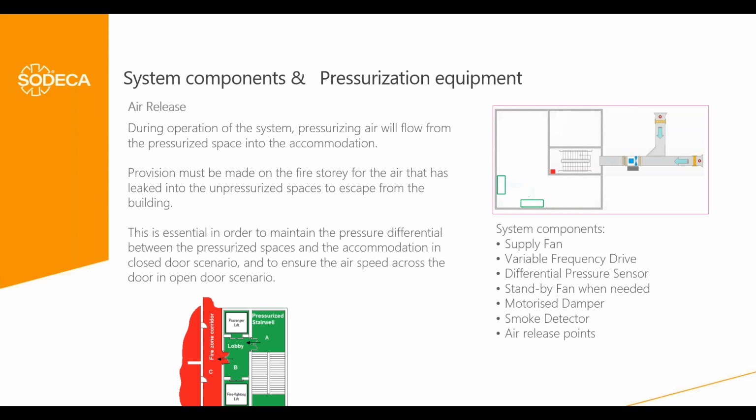The same applies in the door open condition. If we don't have this door open, then the air will not pass through this door, so again the smoke will go into the staircase. So that's why this air release from the non-protected area is necessary.